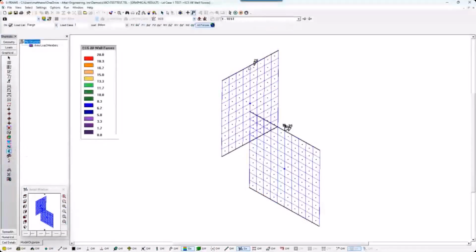And so with these wall forces here, I click on the wall forces tool and I can look at, for example, the wall forces in the local x-axis. And this will show me my in-plane shear force. So I only have in-plane shear force in this particular wall. And I'm looking at either just below or just above that wall location. So maybe just above the wall line location might be more relevant for the base of my wall.